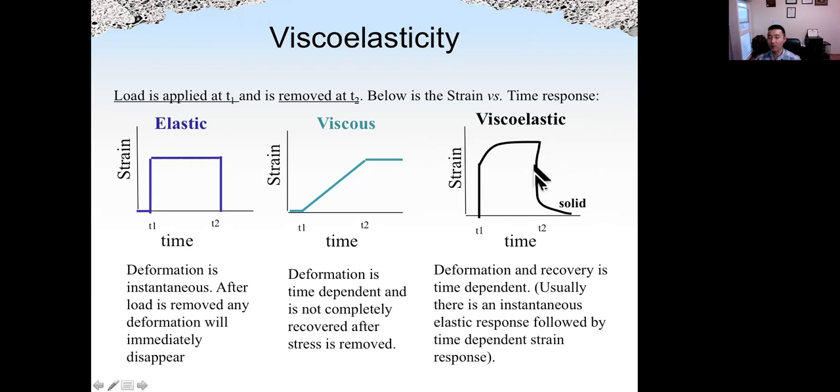At t2, when the load is totally removed, part of the strain is removed immediately, like in this part, but part of the strain is slowly recovered, like in this part. So both deformation and recovery are time dependent, such as concrete.